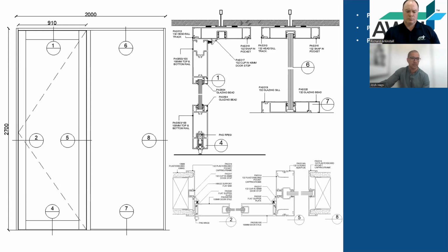A half a length of snapping cap. We're still going to have 1.25 lengths of door stop. Glazing adapter, which is the bit that clips into the 314 on the backside to form your mullion. We need half a length. We're going to have just over 1 meter of bottom bar and bead to form the side light, so I'm going to allow for 1/4 of a length, or 1/4 of 5.6 meters length, also of the snap-in bead.